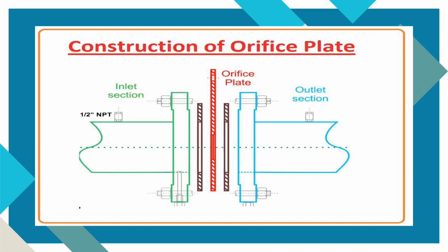It is mainly divided into four parts: inlet section, outlet section, orifice plate, and flow conditioner. Inlet section: a linear segment extending from the device that acts as an end connection for the fluid flowing inside. Outlet section: also a linear segment, similar to the inlet section, where the pressure of the gas and fluid discharge is determined. Orifice plate: present between the outlet and inlet segments and used to generate a pressure drop, which enables the measurement of the flow rate.